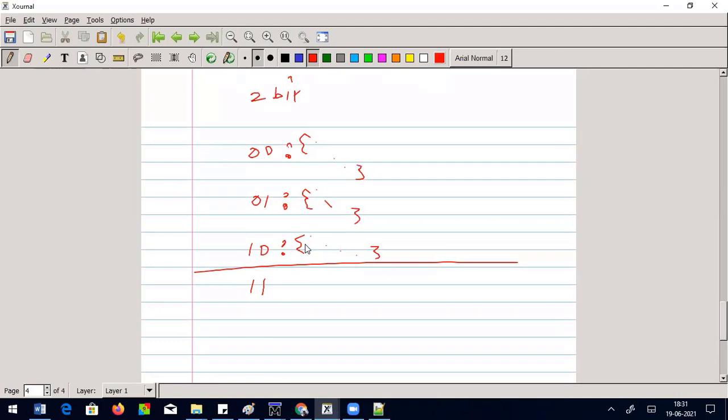I am just leaving it as it is and I write end case. If I do so, then it will create a latch at the backend during synthesis. Why is it so? Because you have left something, and that unprescribed condition will end up with a latch to store that value.